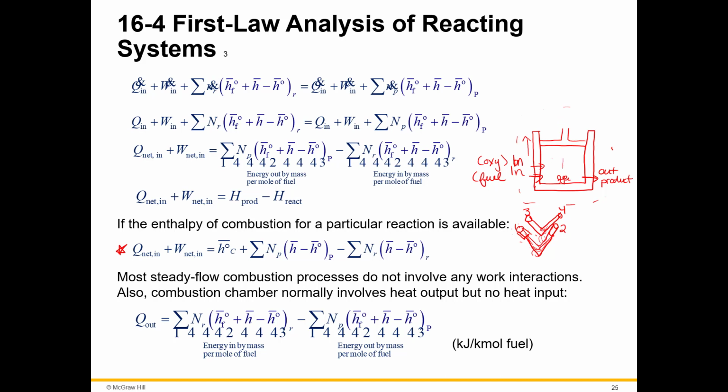And then it's going to compress it. Once it gets to the compression peak, the spark is going to ignite. And that explosion, that combustion right there is going to push this piston into another expansion. And then when it comes back up to compress, it's going to push out the product, the vapor. And it's going to do it over and over again because this is a cyclic motion.